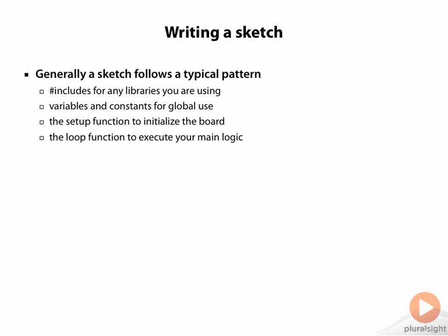At the top of a file, you can put variables and constants that are there for global use. Again, you have the setup function that's going to initialize everything the way you want. You'll set up the digital pins or the analog pins the way that you want, set up any other runtime variables, and then the loop function just executes over and over and over again.